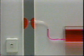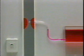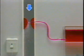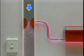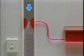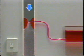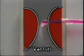Now, let's narrow down the mouth of the tube to speed up the airflow and see what happens when we try it again. As you can see, the liquid is atomized, that is, changed into a mist that can be blown out through the pipe. This is basically how a carburetor works. The portion that was made narrower to speed up the airflow is called the venturi.